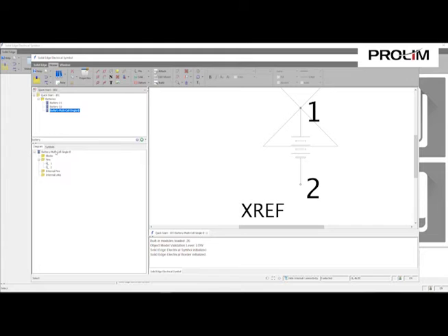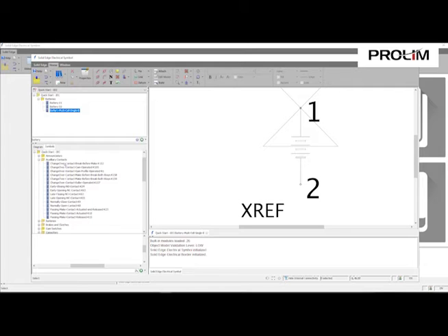But we do have another option that we can use to examine things before we work with them. If I click on the symbols tab here, you can see that I still have access to all these different quick start libraries. If I pull down this IEC, so we were up here before in the design window looking for batteries, but down here I can actually expand these windows. And if I want to get a quick view of what these icons look like before I ever start working with them, you can see I'm getting this little preview down here at the bottom. I can do that anytime that I have an active symbol open over here.